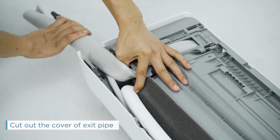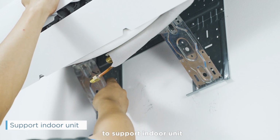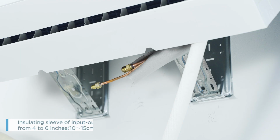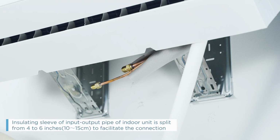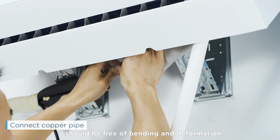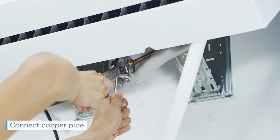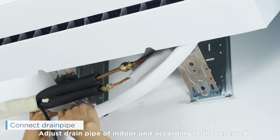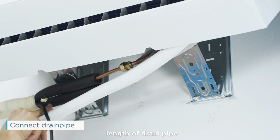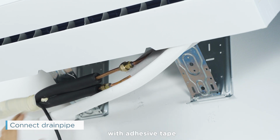Remove the drain pipe. The installation auxiliary bracket is threaded through the hole of the mounting plate to support the indoor unit. The insulating sleeve of the input-output pipe of the indoor unit is split 4 to 6 inches, 10 to 15 centimeters, to facilitate the connection. Connect copper pipe. Note that copper pipe should be free of bending and deformation. Adjust the drain pipe of the indoor unit according to the reserved length of the drain pipe. Note that the interface should be sealed with adhesive tape.